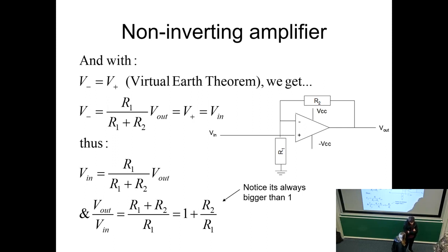Sorry. So what you've got, you've got a resistor and a resistor. This end is at V out. This end is at 0. And this is the minus point that you're interested in, so that's a potential divider.